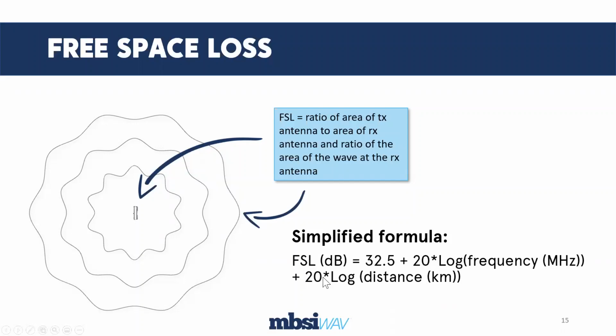32.5 plus 20 log of the frequency plus 20 log of the distance. That is the loss that we would expect to see in a signal transmitted from one point and received at another point some distance away. So we can see here a couple things.